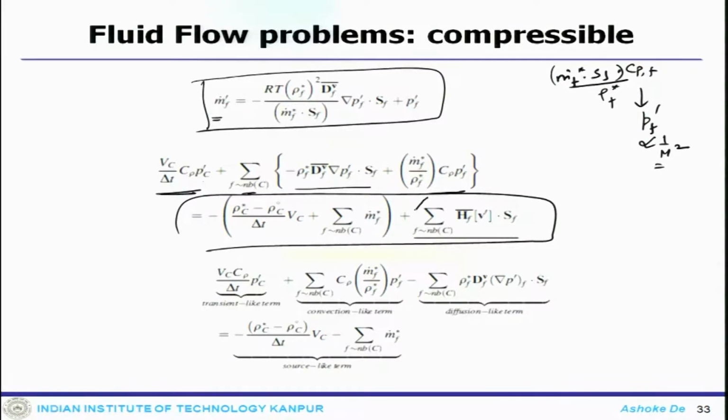So, how you actually treat this term gives you various SIMPLE algorithms, which we have already seen in the case of incompressible flow, where SIMPLE, SIMPLEC, PISO, it depends on how we take care of this correction term.